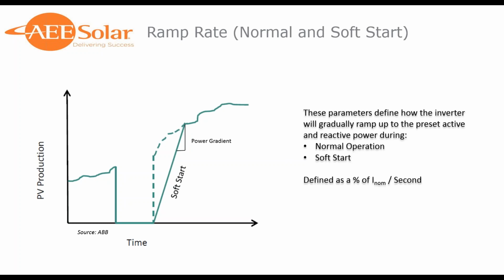So what we see here is the inverter is ramping up. Looks like maybe a morning cycle. And then for whatever reason, it drops offline. Either the grid disqualified, or I suppose it's possible that this was based on a timeout. I think a disqualification is the scenario they had in mind.